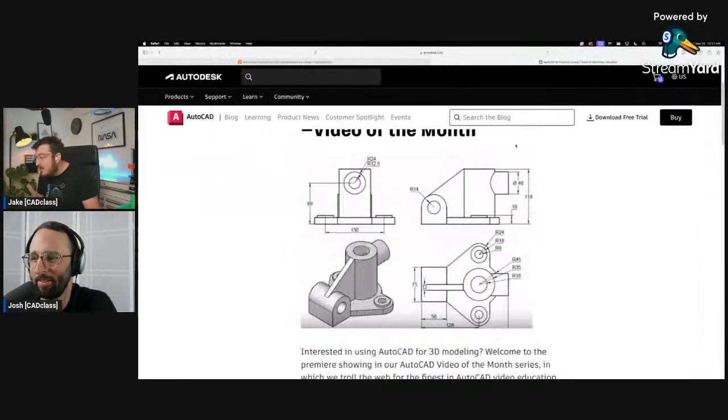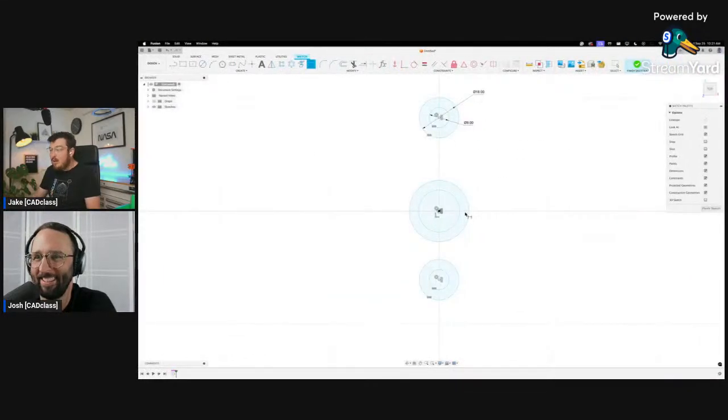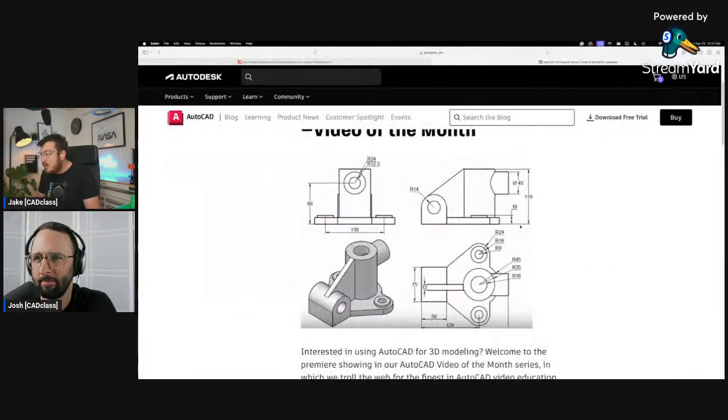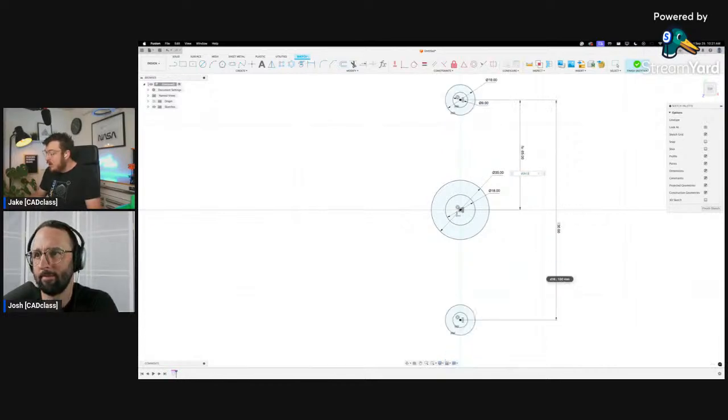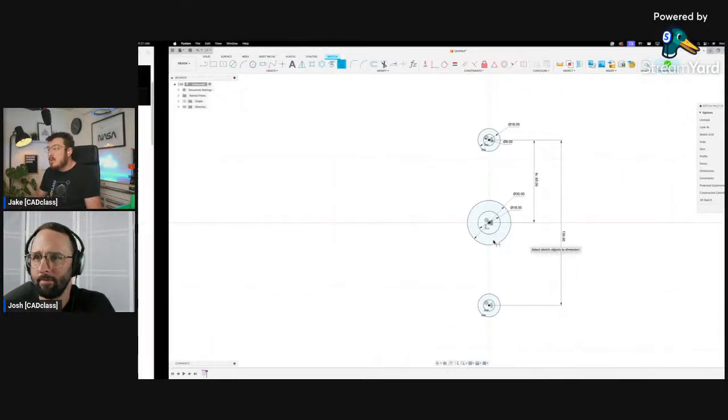We can host one of those. It's going to be 18 and 35 for the large. Okay, 18 and 35. So then these, I don't know the distance between the centers, do we? Oh, 130. Okay, so then let's split that. So you can go 130 between that. And then I'm going to say the distance between these 2 points is going to be that number divided by 2. There we go. So now that's nice and equal.